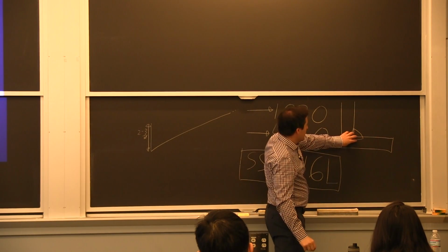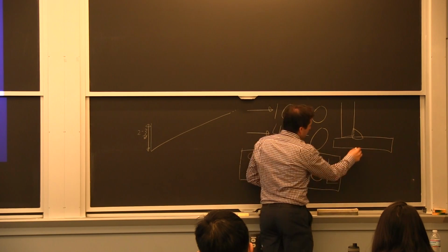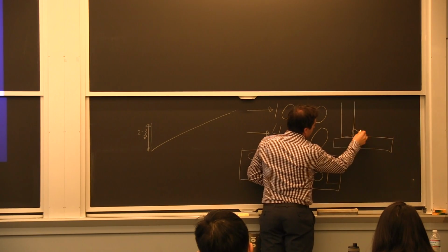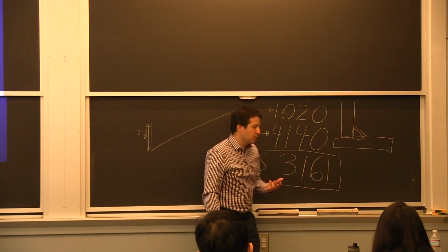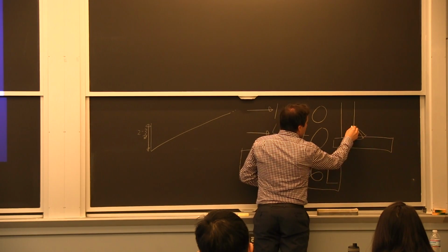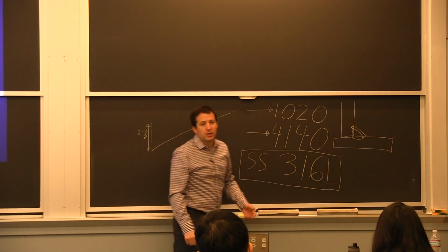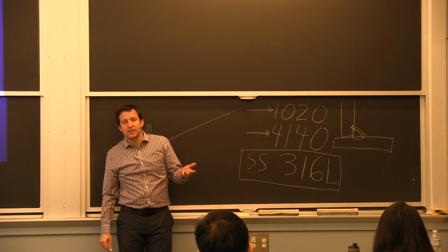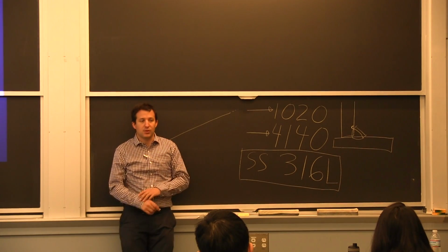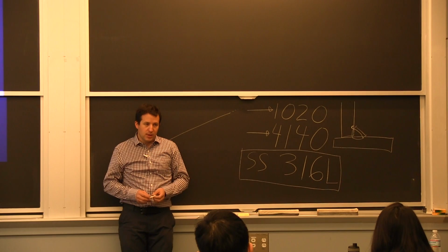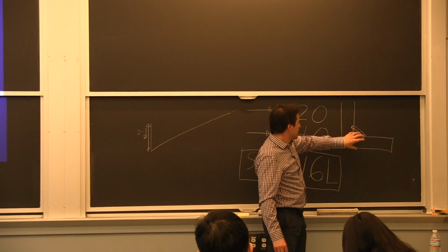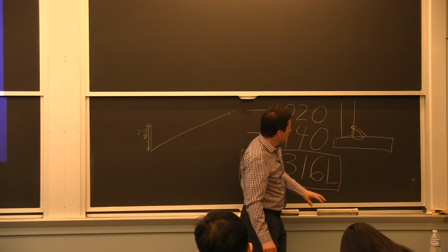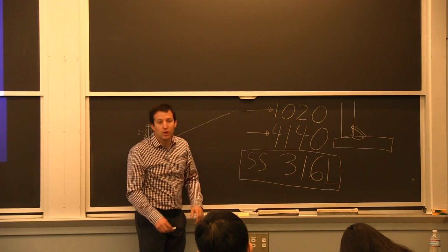if this T-connection goes through weathering with chlorides, it's possible that my weld here will hold strong because it's got a good chemistry. The metal right next to it here is what needed to be protected during the heating and cooling process in the heat affected zone, and that's where you can have the chrome depletion. So to alleviate this, these details of the welding process and the shielding gas can go a long way.